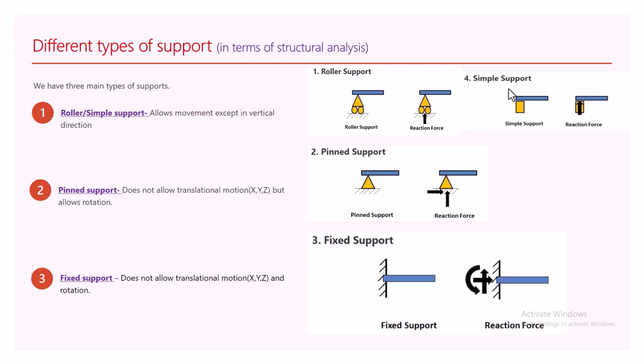The third one is the fixed support. So you see that movement in all three directions is not allowed. You're not allowed to rotate, you're not allowed to move up, and you're not allowed to move horizontally.